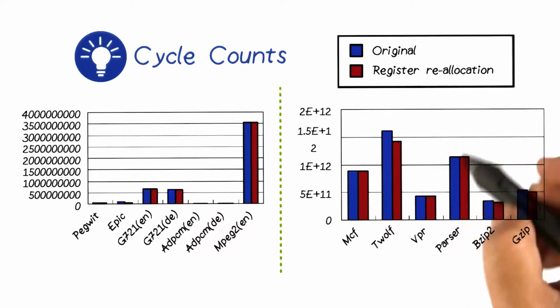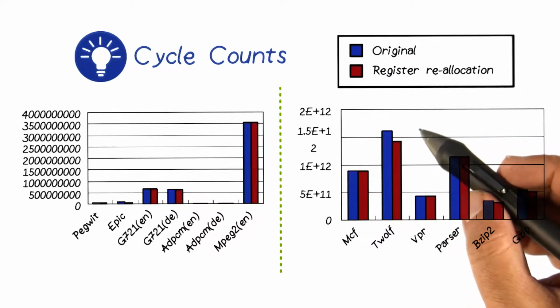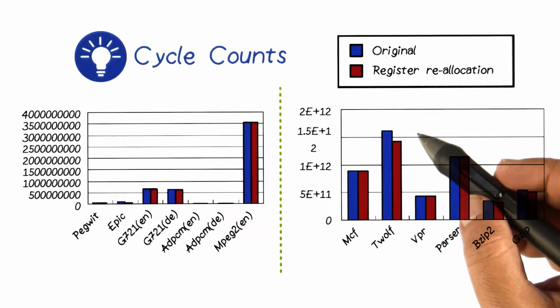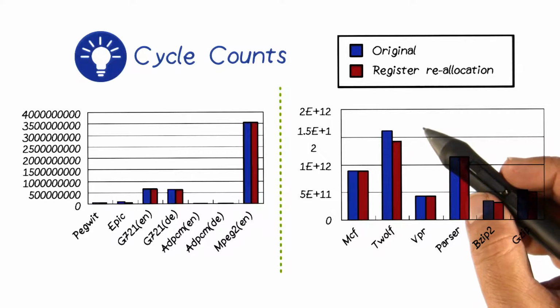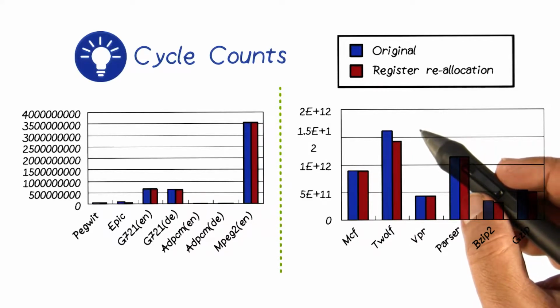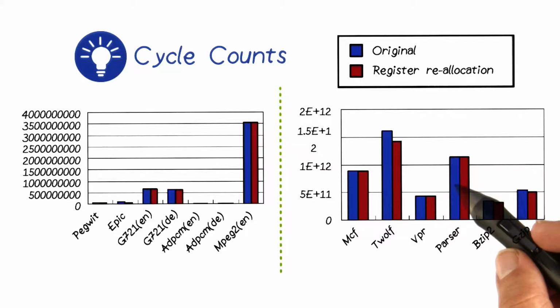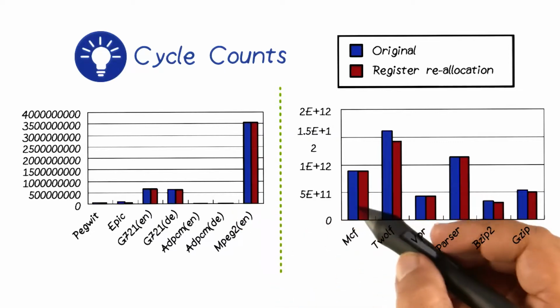On a different architecture which doesn't hide the latency by dynamically reordering the instructions in the hardware, which is quite typical of the embedded processors, we could potentially see more benefit in terms of cycle counts as well, and that's something which could be evaluated on in-order architectures or processors, where such benefits of removing dynamic load stores translate into latency reduction or a smaller number of cycle counts of the program.